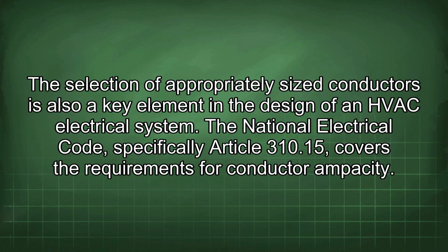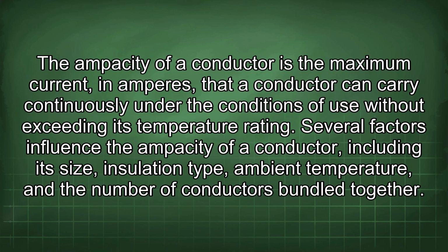The selection of appropriately sized conductors is also a key element in the design of an HVAC electrical system. The National Electrical Code, specifically Article 310.15, covers the requirements for conductor ampacity. The ampacity of a conductor is the maximum current in amperes that a conductor can carry continuously under the conditions of use without exceeding its temperature rating.